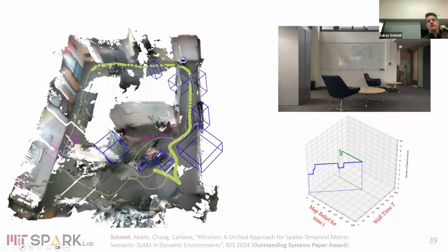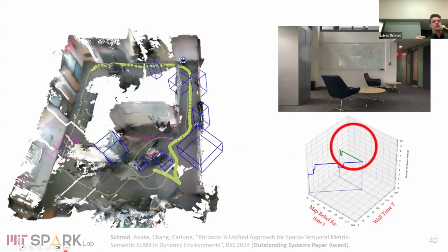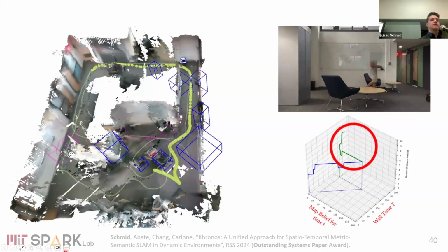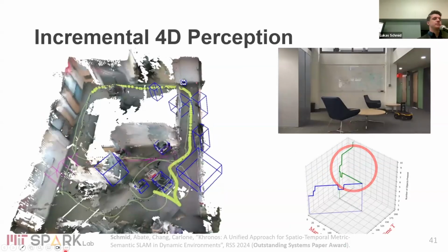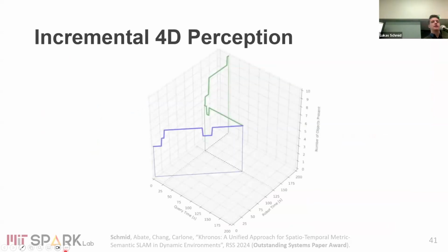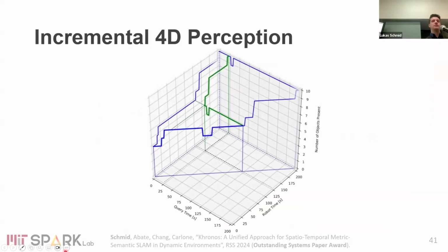And in the same fashion, it's actually really cool if we just care about what the world was like at lowercase t equals 20 seconds, and the robot gathers more data in the future, we can see how the background becomes more complete, it becomes more optimized, and more objects are detected. So we also have this flow of information back through time. In this fashion, we can now for the first time optimize over histories of dense reconstructions on board mobile robots.